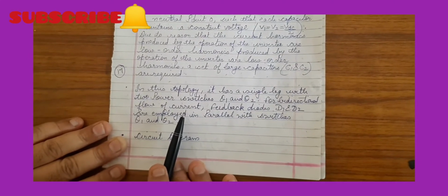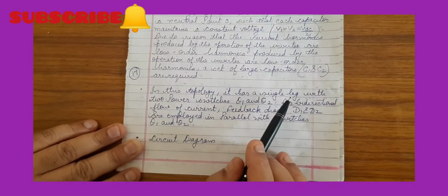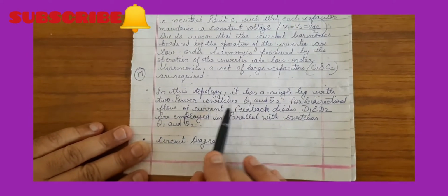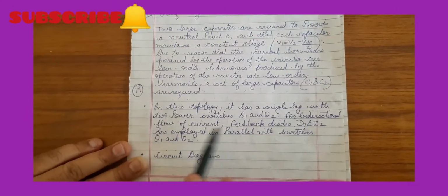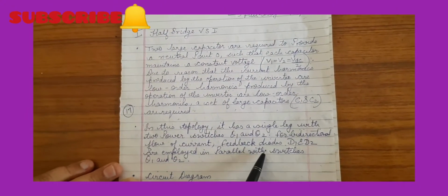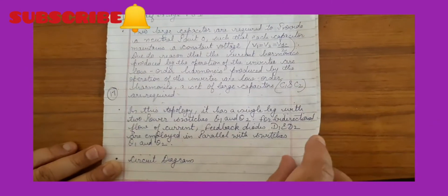Now in this topology, the half bridge voltage source inverter, it has a single leg with two power switches, that is Q1 and Q2. We will see in the circuit diagram. For bidirectional flow of current, feedback diodes D1 and D2 are employed in parallel with switches Q1 and Q2. The circuit diagram is shown in the figure.